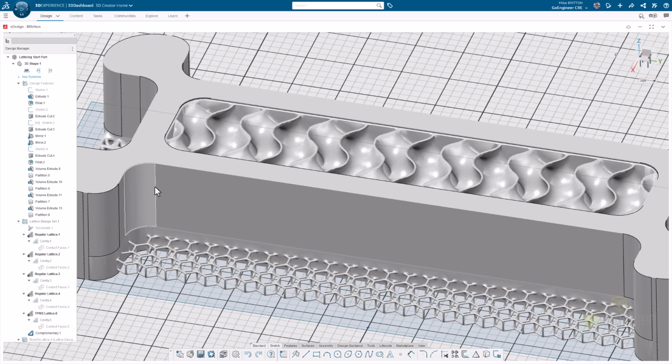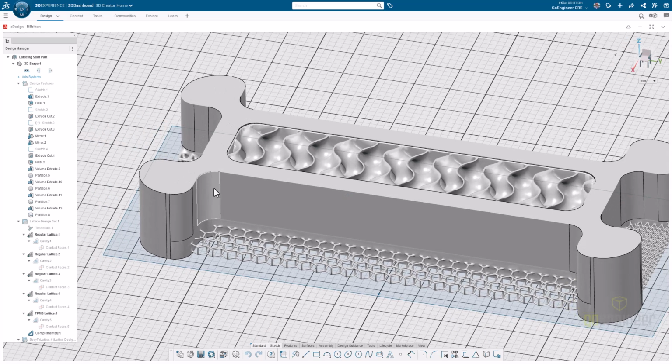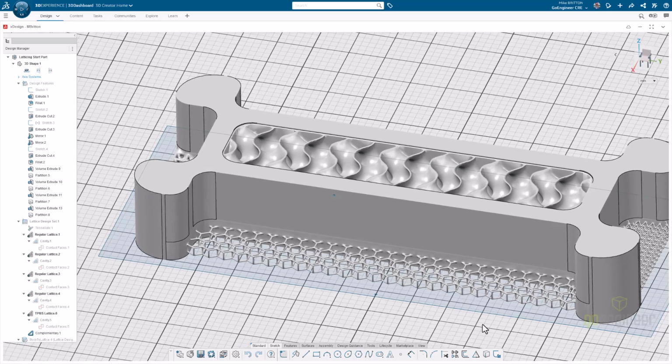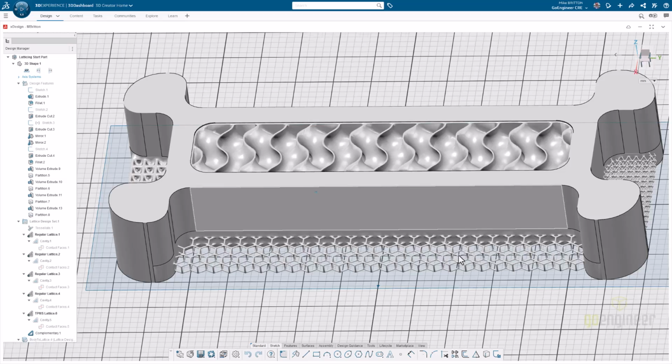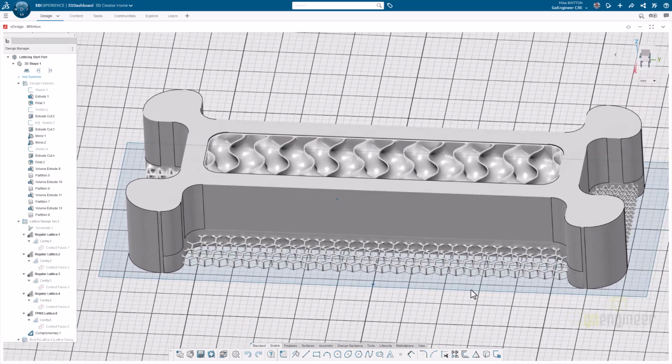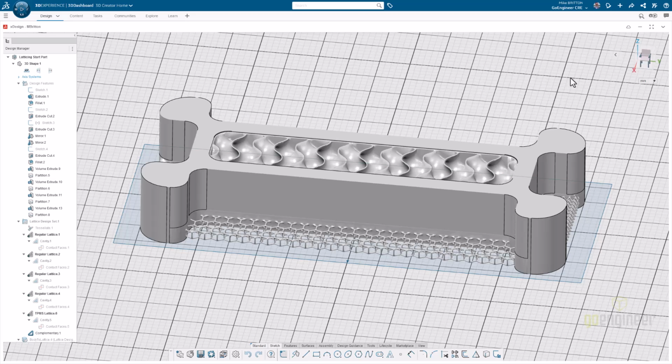We are still getting our arcs and true NURB surfaces out here where they are relevant inside of XDesign, but we can see that the lattice is coming through really nicely. In our rich client, to send this out for 3D printing, we could hit this equivalently placed arrow. In the web clients, this does some other stuff, but what I can do here is just use this to export, and I could export this as an STL or a 3MF file to prepare this for 3D printing.